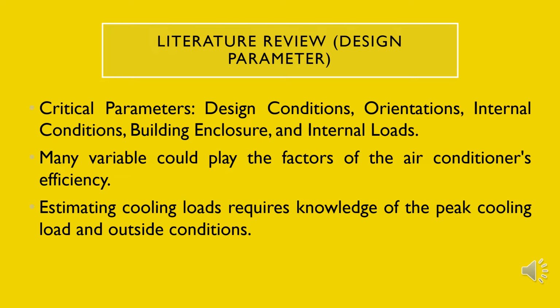Five critical inputs must be taken into account when developing design parameters in order to achieve the desired HVAC system. First, design condition. Second, orientation. Third, internal condition. Fourth, building enclosure. And lastly, internal load. The amount of heat gain or loss through a building is determined by the outside and